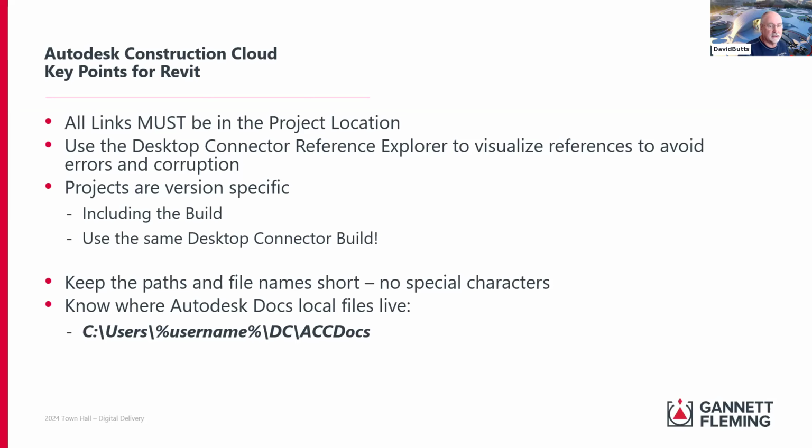We constantly see errors where people are having files that are out of date. They're not cached. They're not working correctly. You probably have seen some people talk about you need to clean up what's called your collaboration cache folder on your C drive, or your temp folders on your C drive. So if I'm getting an error that says this model is corrupt and needs to be reviewed, or needs to be tested again, or it cannot be opened, most of the time it's because you got out of date collaboration cache files.